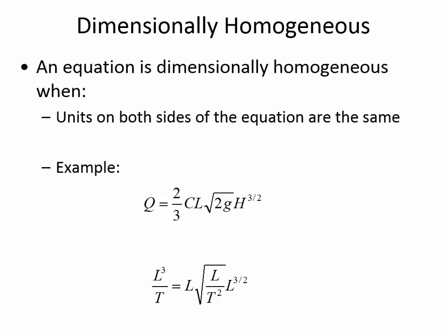And when you break it down into the most fundamental terms, there's only 3 units out there. There's length, mass, and time. And every other unit is some rearrangement of those 3 base building blocks, length, mass, and time. And so here we abbreviate. Anytime we want to look at whether a formula is dimensionally homogeneous, on the left-hand side, we know flow rate would be, for instance, cubic meters per second, and so that's length cubed per time.